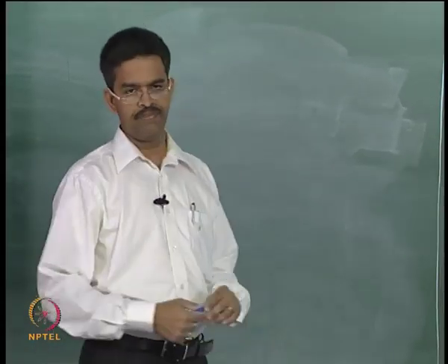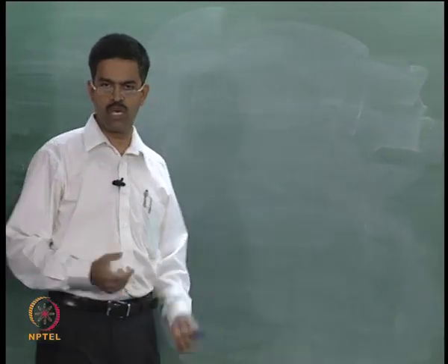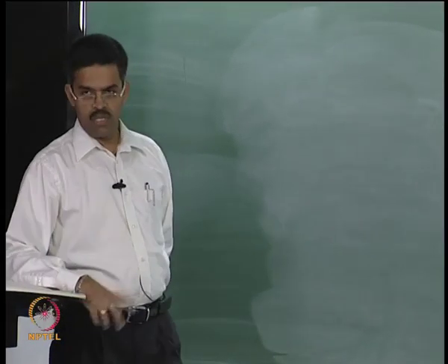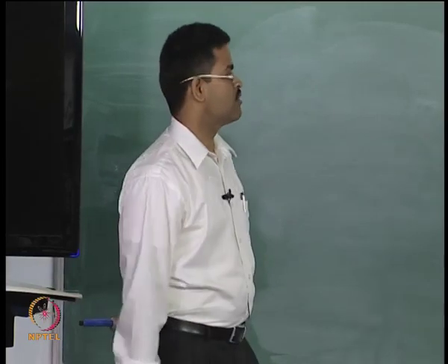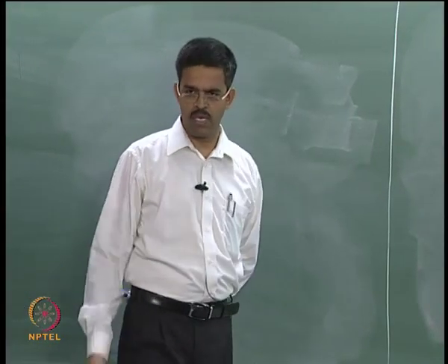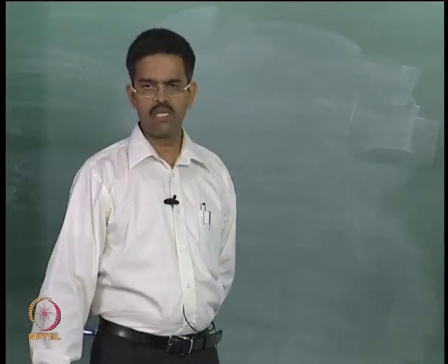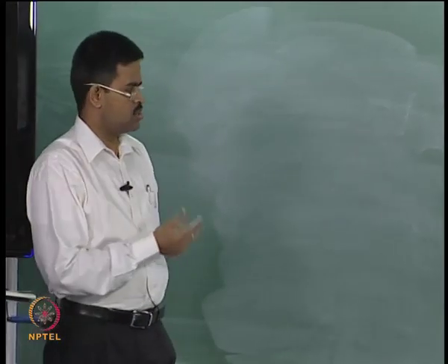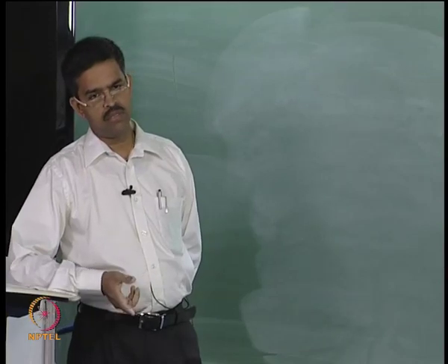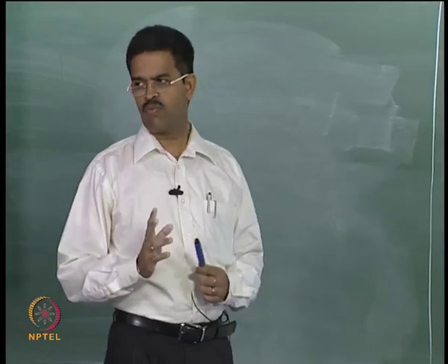I will show you that here now by an example, simple 2 degree freedom system example I will pick up and I will show you that how the normalization of weighted modes will help you in solving the equations of motion for a multi-degree freedom system. Single degree there is no problem, we already know the solution, there is no difficulty. For multi-degree there is a difficulty. Let us say how can we use the procedure of normalization or orthogonality principle in using this for solving MDOF systems comfortably. That is our focus. Okay.